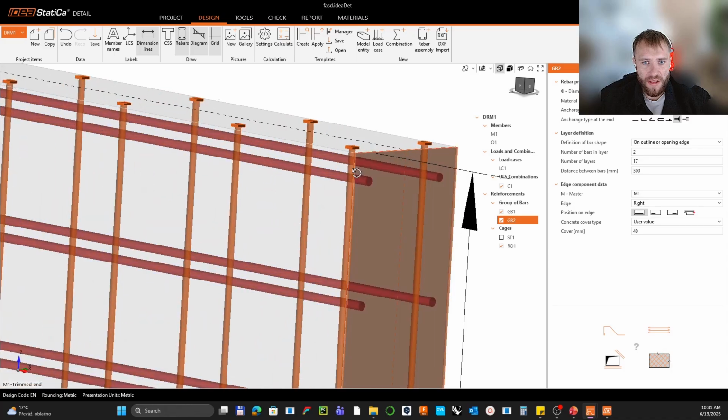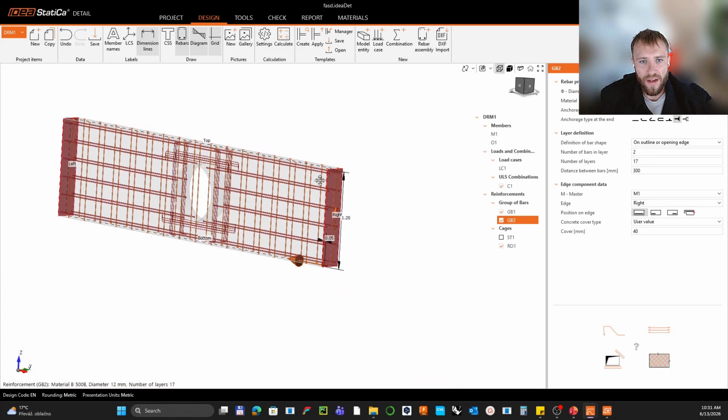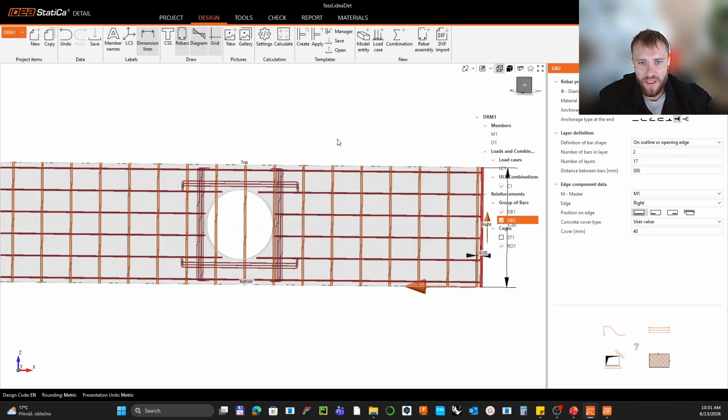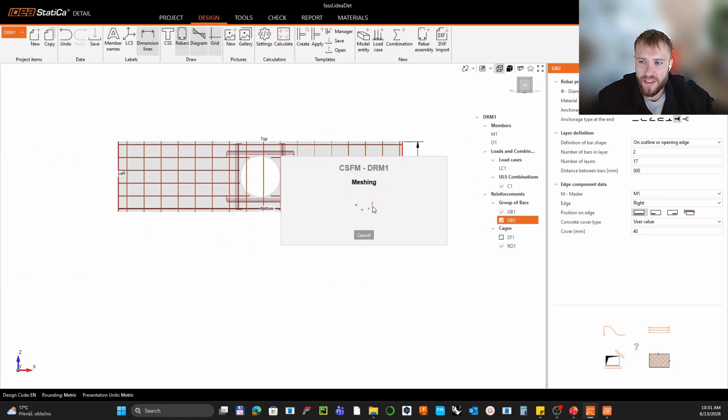You can see, it will enable you to put there the top layer of the reinforcement bars. Perfect. So actually, it works well. I can just run it and see the results. It will lead to a decrease of the stress in the compression. Why? Because the reinforcement bars, with the portion of the stiffness of the bar, will absorb some level of the compression.